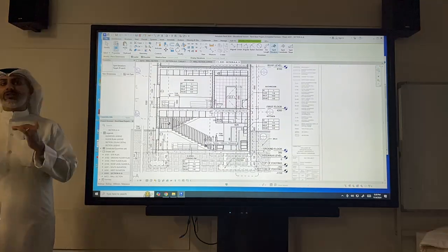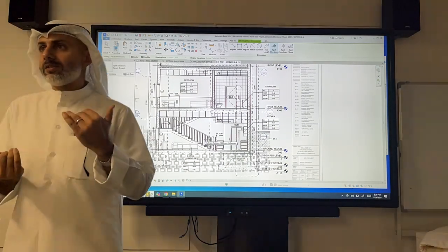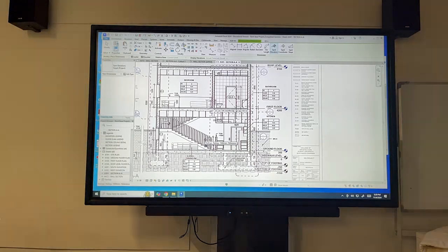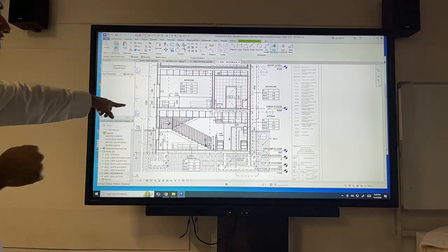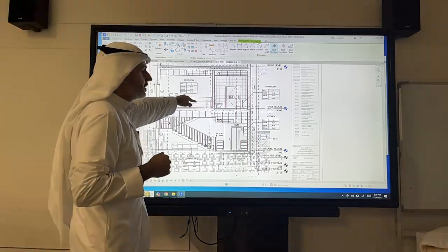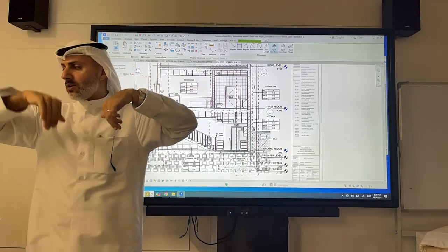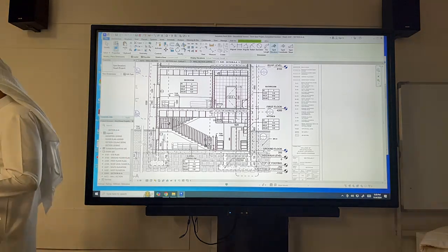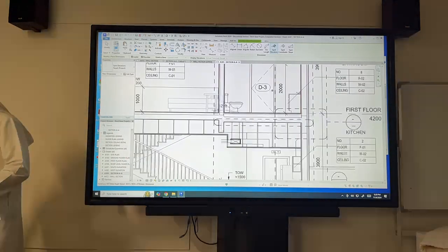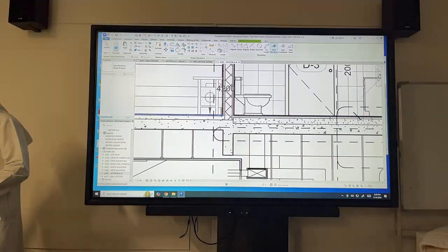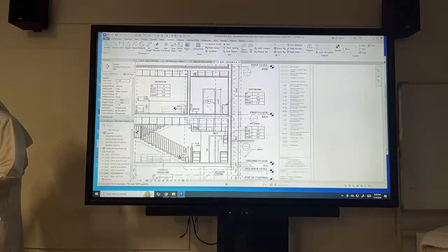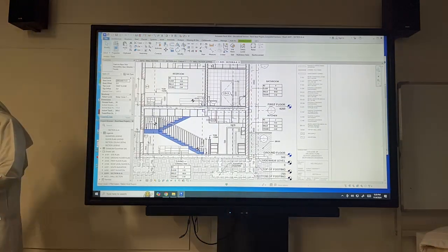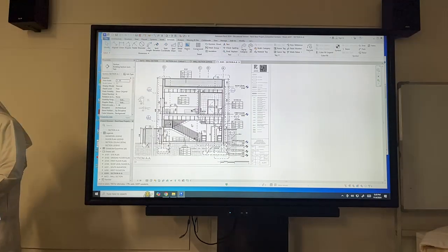So we're going to put spot elevation and change of levels. We have the dry area first, then the landing, and then the landing above. So we're going to add one at 300 and add one after we make the dash here. Where we're landing here is level 4,200. So one that's probably going to be somewhere here. And you have the dashed lines to take you up.